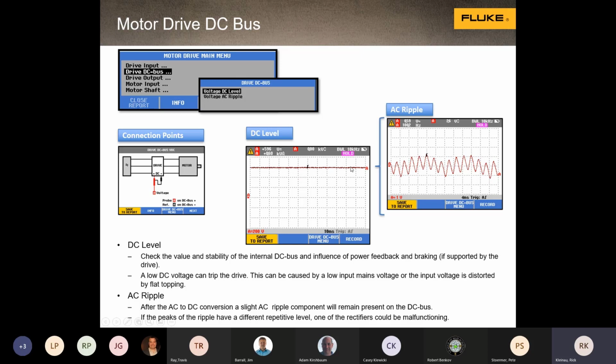If you're a scope user, you can do that. You can AC or DC couple the measurement input on a scope typically. If I take the DC out and I'm AC coupled, I'm only looking at the AC waveform here. So now I can blow it up. I'm at 1 volt per division on the scale for the ripple. But the bus should be close to 700 volts, right? Well, 596 volts. That's why you can't see a 1 volt ripple sitting here. You have to be able to separate the two, and with the firmware loaded in the MDA, that's easily done.